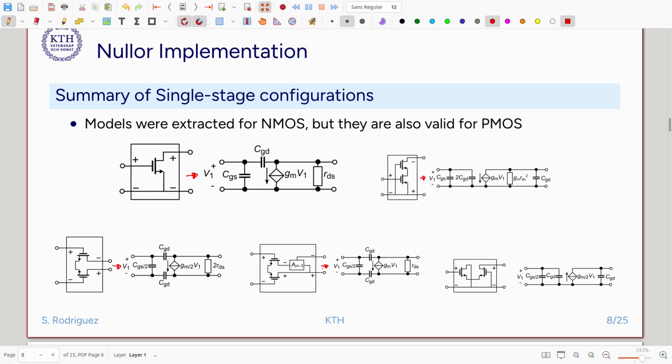Note the difference: in the differential pair we have half of the transconductance working, and on the other hand, here we have the whole transconductance working due to the current mirror effect. And we have also the long tail pair here. Okay, so those are the basic building blocks that we will be using during the implementation of multiple stage feedback amplifiers.